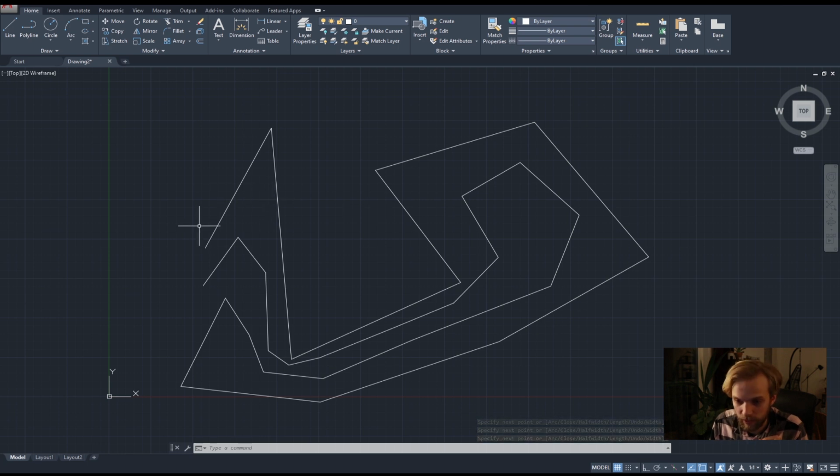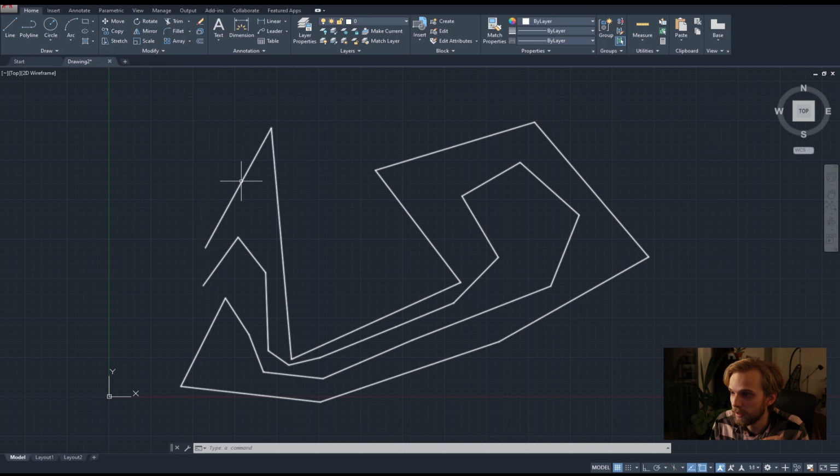So now this is a polyline rather than a line tool. If I click on this, you can see that everything gets selected. This is a type of geometry that consists of multiple lines, and all of them are joined into a chain of lines. It's super convenient for selection purposes. It's super convenient to work with, and it doesn't really have any drawbacks. Almost all of the lines that I draw during the design process and the technical process later on are polylines, not lines. Keep that in mind.